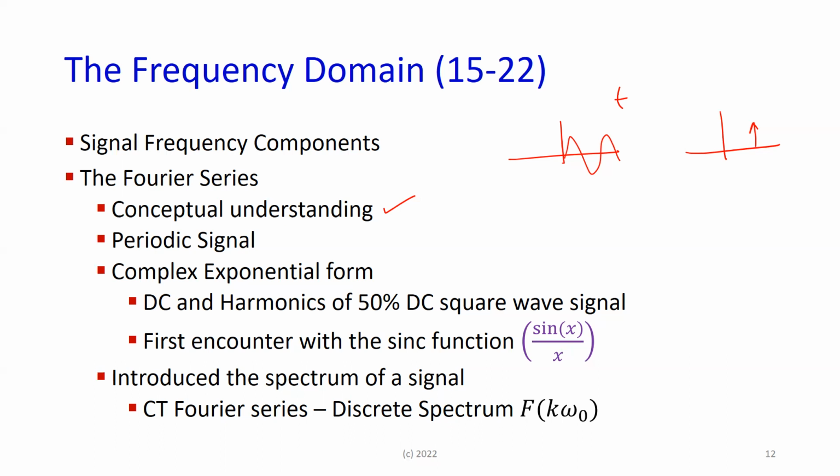So back to what we had said before, if I know how a system works for a sinusoidal input, then for some arbitrary signal, I know that the arbitrary signal, because of its Fourier series components, is broken up into a series of sinusoids. So therefore, I could deduce what the behavior of it would be for all of the sinusoids that it's likely to encounter.